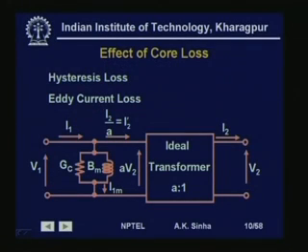As soon as we excite the transformer, this is going to happen. So, this is going to be there even at no load. This is dependent on the voltage that we use to excite or energize this transformer. Therefore, we have put this as a parallel branch.